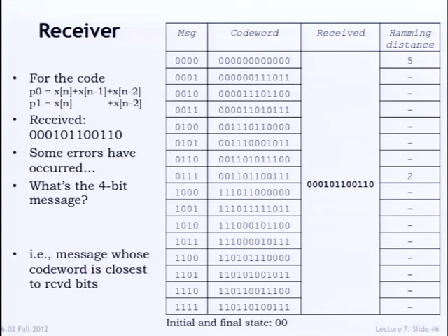So what I'm actually doing here is I actually have a message that's this followed by 2 zeros. And so if you're trying to connect these two columns with the trellis that I had on the previous page, that's how you should think about it. Okay, but with any particular message, you navigate up and down in the trellis. Okay, this particular one, you navigate up, up, down, up, and that's the sequence that's generated. That's the code word that you would expect if this was the message.